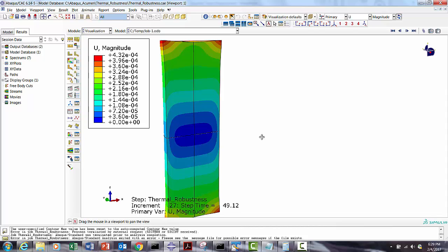So there are a lot of places where you want to do this coupled temperature displacement analysis. Heat transfer combined with structural engineering, like sudden cooling and thermal shocks. Like an engine part: if the engine doesn't dissipate heat quickly, then a gradient is generated within the engine cylinder, and that requires thermal robustness capability for the engine.